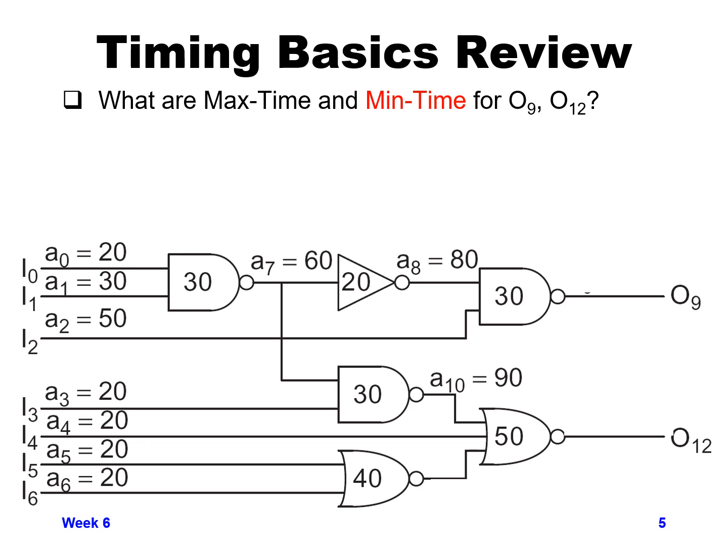Now let's go to the NOR gate below that. That has 2 inputs, I5 and I6, which are coming in at timing A5 and A6, both at 20. So both are at the same time. So we take the 40 picoseconds delay through the NOR gate plus the 20 gives us 60 picoseconds.